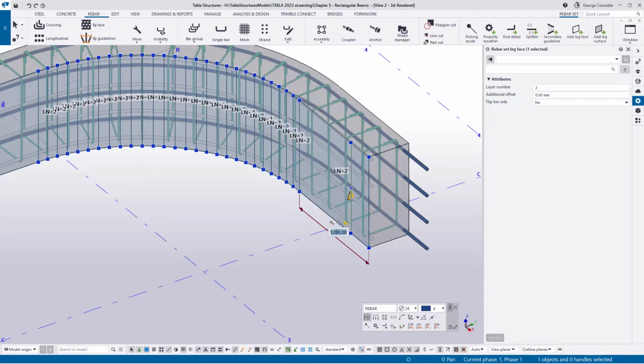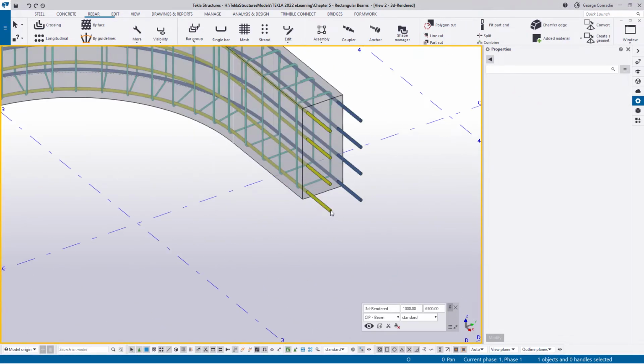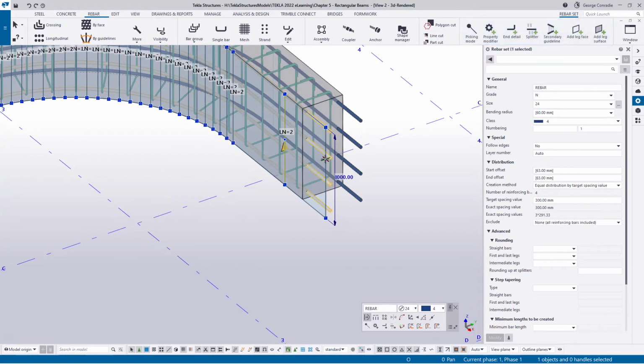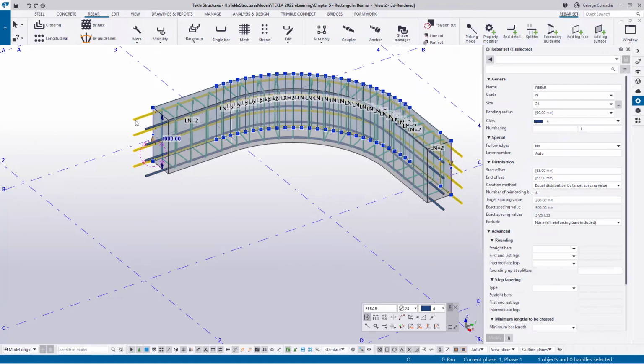If I do that, Control A, and I say 1600, and I extend the face there. What happens now is that this bar on the inside recognizes the faces all the way to there, but on the outside, the face stops here, and that's an extension, an end extension.